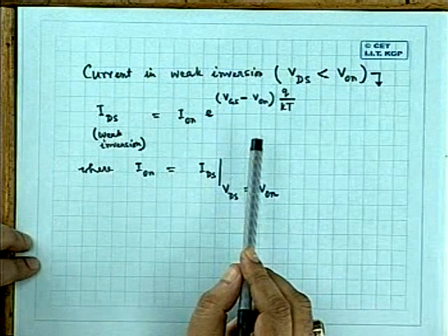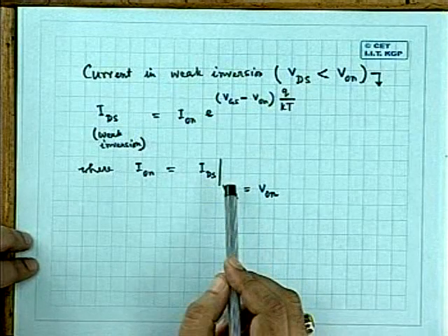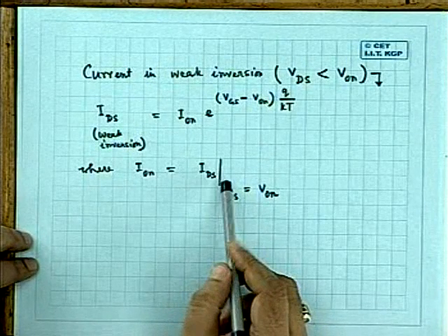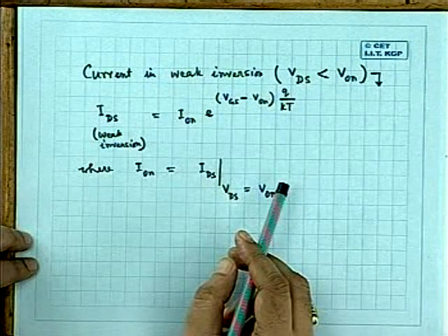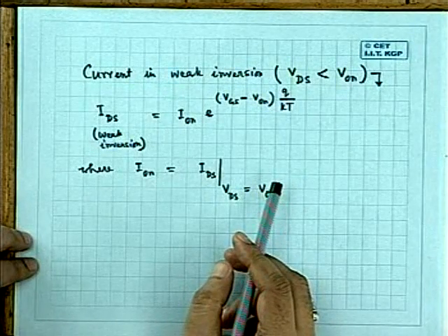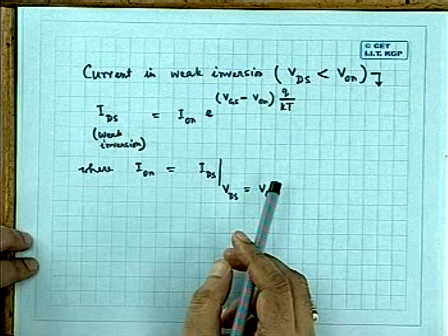and that is typical for the diffusion current. You remember the subthreshold conduction is primarily due to the diffusion of carriers. Drift of the carriers is not important in subthreshold because the current is very small and the potential drop is small. The potential gradient along the channel is very small in subthreshold, but it is a diffusion current, because subthreshold means you have still reduced the barrier at the source.